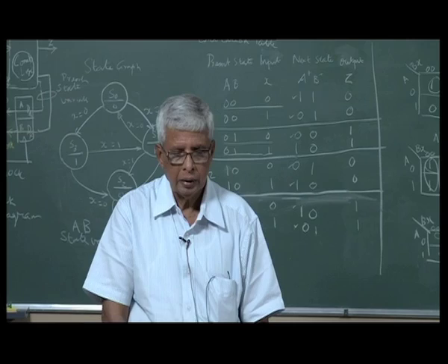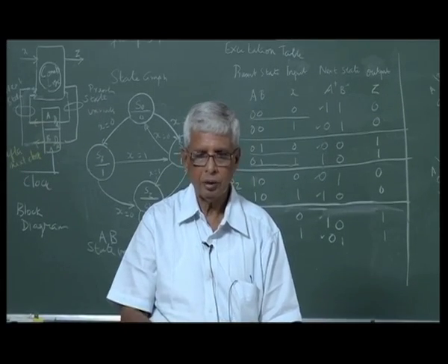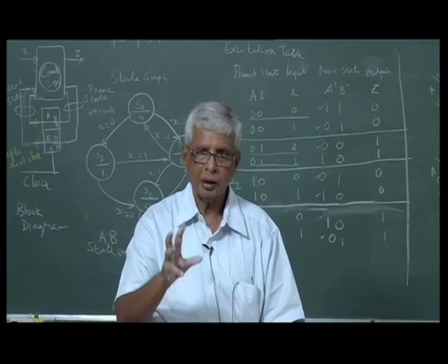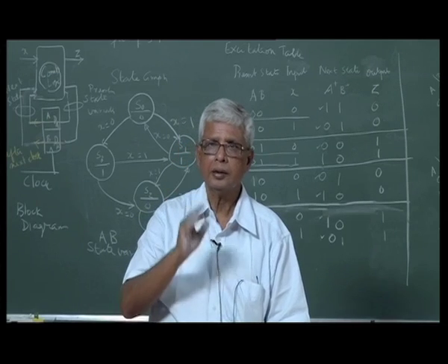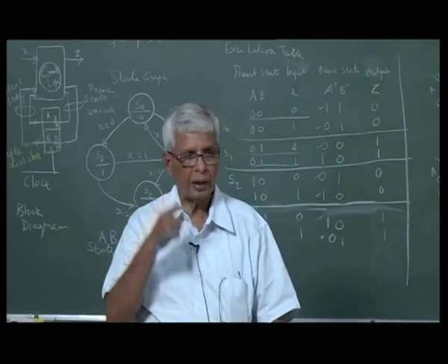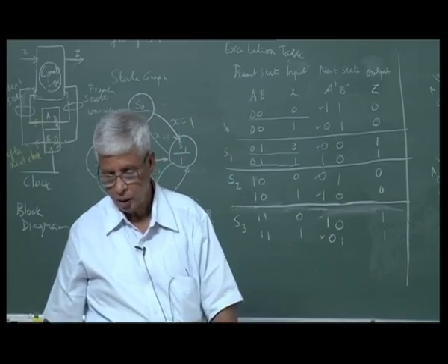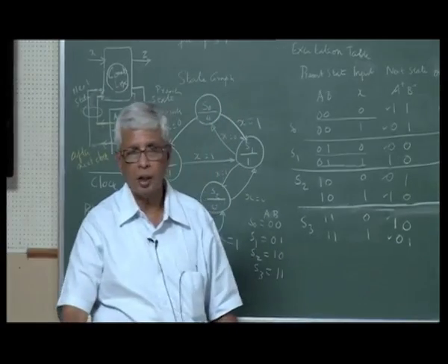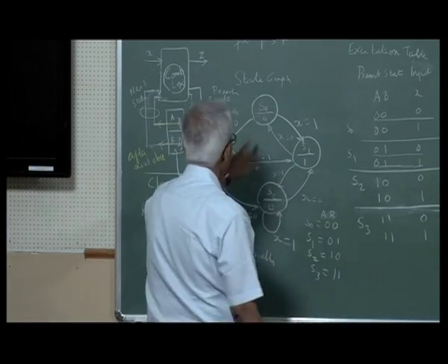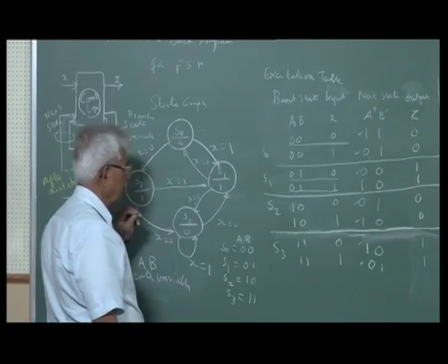Then in up down counter we had our input. When x is 0, we have to count up. When x is 1, we have to count down. So again same as counter state diagram with x equal to 0 or 1. Today what I have done is a generalized model where I said there are outputs also possible. States, inputs and outputs, and we draw the state graph accordingly. For that only you do this.